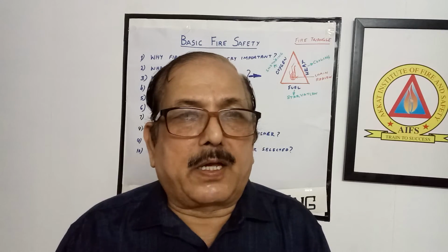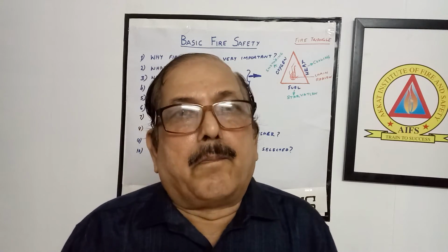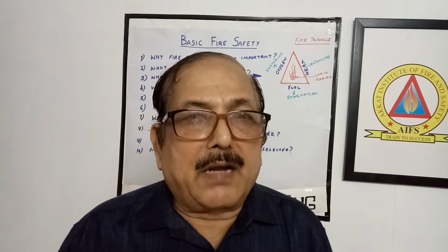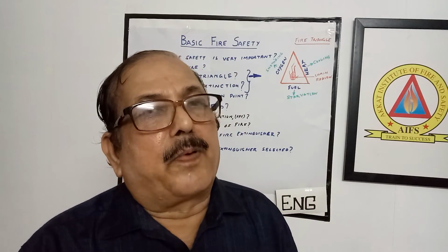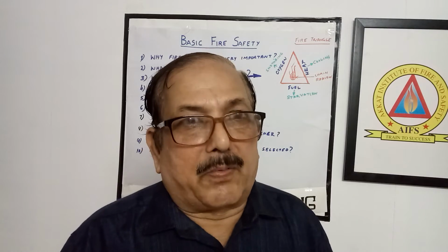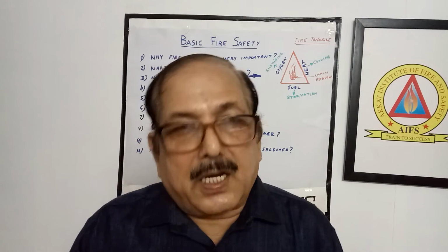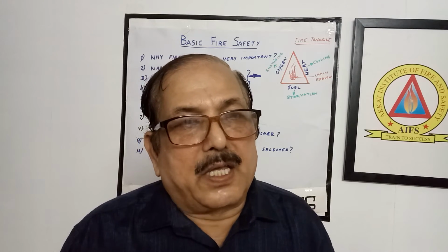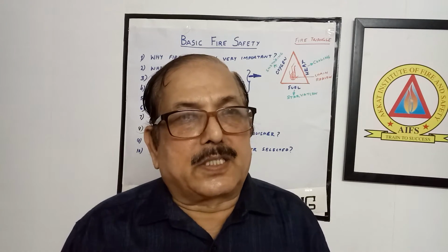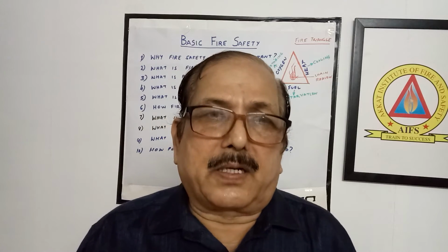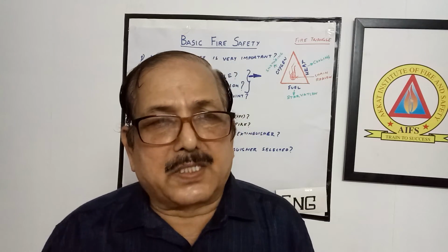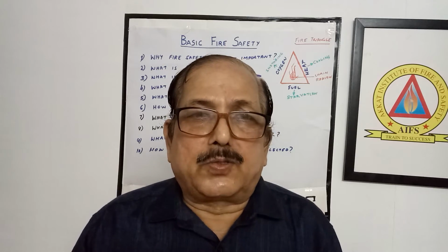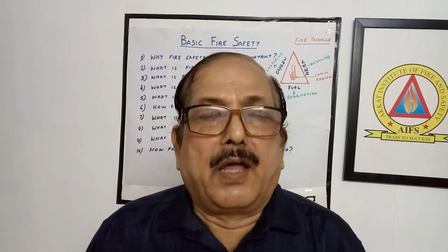You know why they are common? Because in many places electrical fire is very common. So whenever there is an electrical fire, you can operate with the CO2. That's why CO2 is available there. Then for all other types of fire, whatever may be there, class A, B or C, it is suitable for this DCP. So that's why these two types of fire extinguishers are very common.